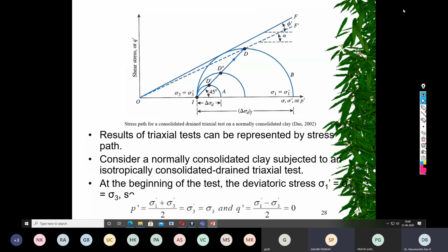Here it is shown as linear, but this linearity pertains to the total stress analysis. Suppose for the same sample and the same imposition of delta sigma d, you draw the same thing for effective stress analysis, would it be linear? Maybe or maybe not. We do not know.